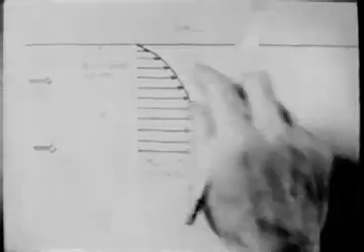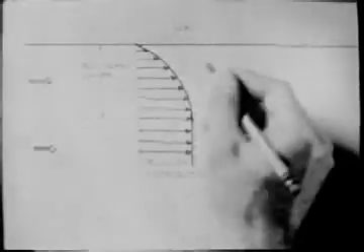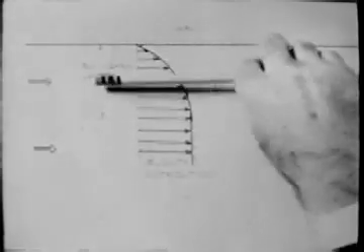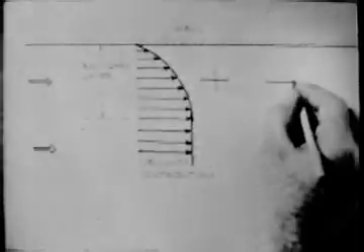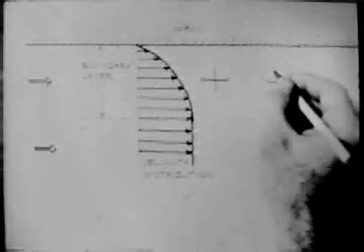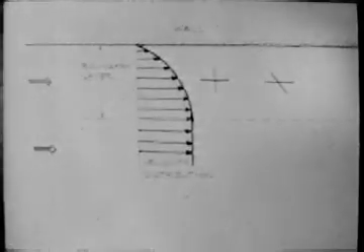Near the wall is a viscous boundary layer, in which the velocity increases with distance from the wall. Let's look at a fluid cross. One leg moves downstream parallel to the wall, while the other leg rotates because of the non-uniform velocity distribution. So there's a net vorticity, and the vorticity meter spins.